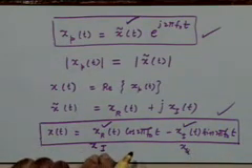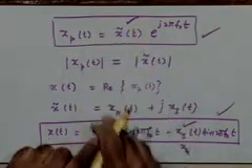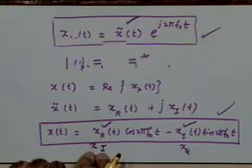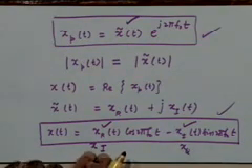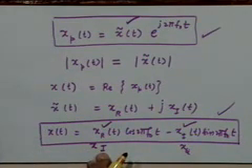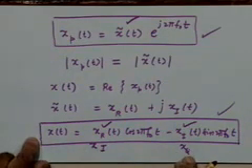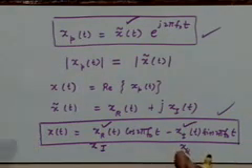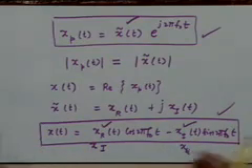In many books you will find the notation x_I(t) and x_Q(t) to indicate the in-phase component, which is a low-pass signal, and the quadrature phase component. What it also means is that a bandpass signal can be resolved into two low-pass signals, one of which is the in-phase component, the other is the quadrature component.